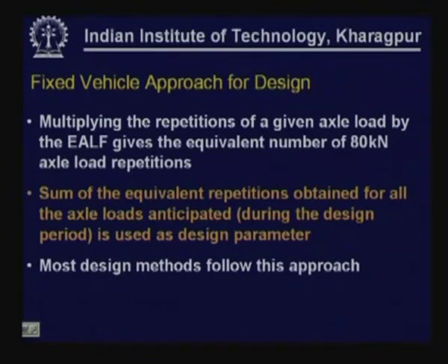The sum of all these equivalent repetitions obtained for all the axle loads anticipated to be coming during the design life period is used as the design traffic. This number of equivalent standard axles is the design input. Most of the design approaches follow this method of considering pavement traffic in pavement design.